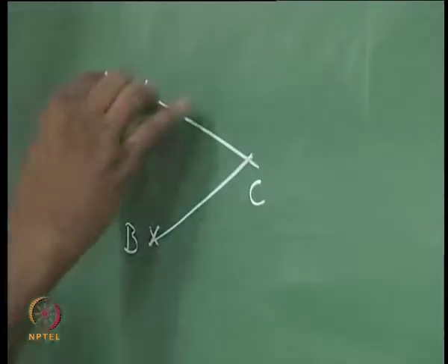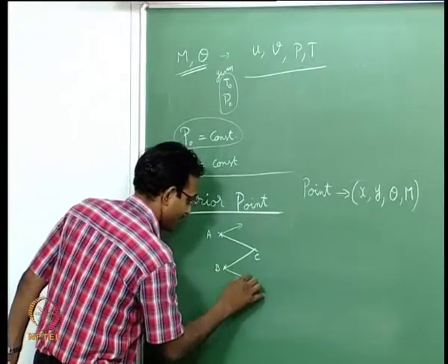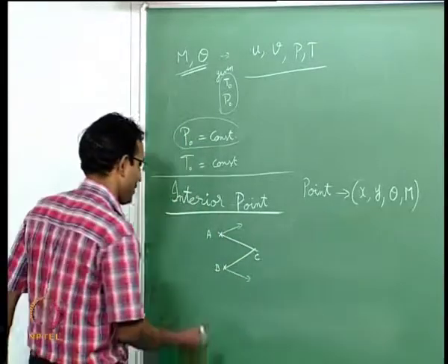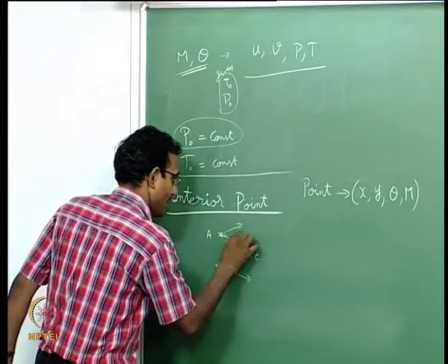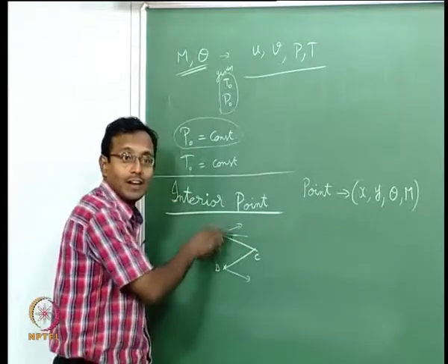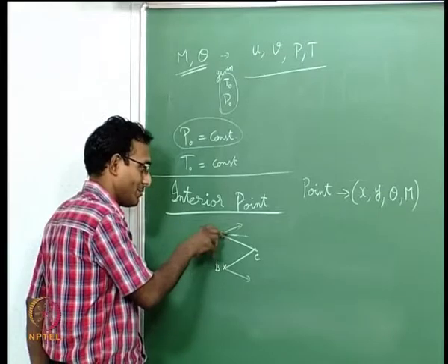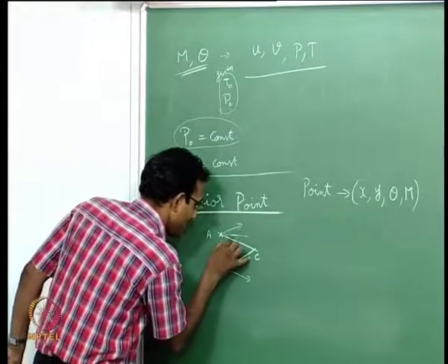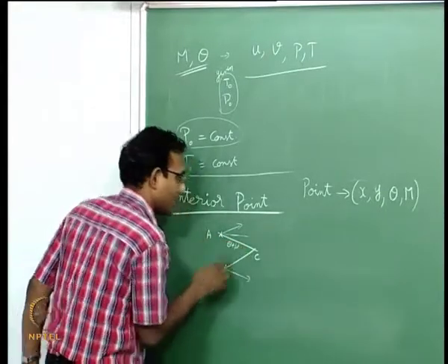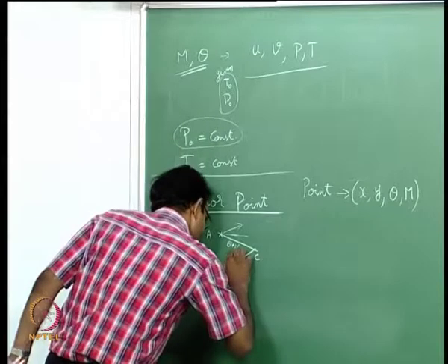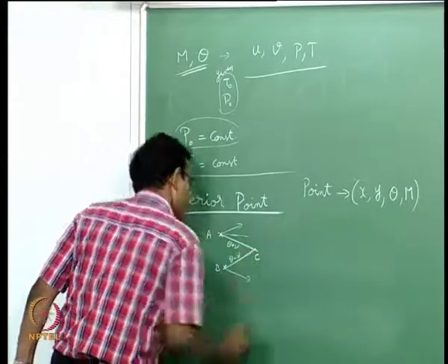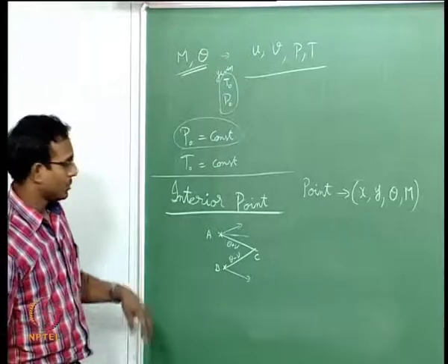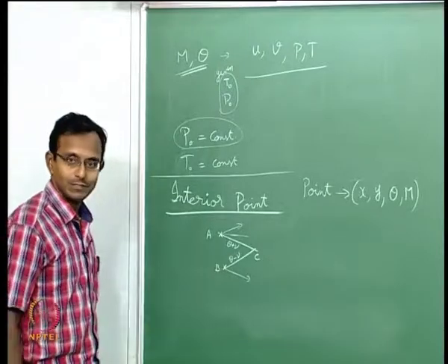So what should I do? Let us say the velocity vectors are like this, with arbitrary values. Now I have drawn a right running characteristic, or a negative characteristic, from A, which means theta plus nu is a constant on this line. On the other line, theta minus nu is a constant. A positive characteristic will have theta minus nu constant.